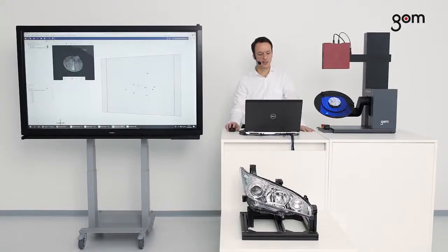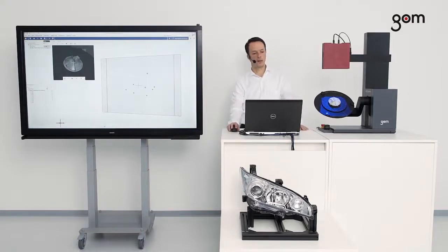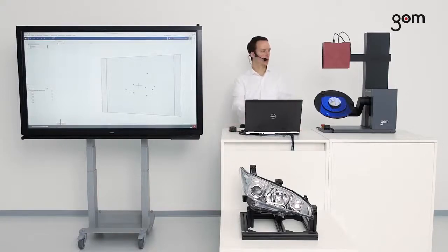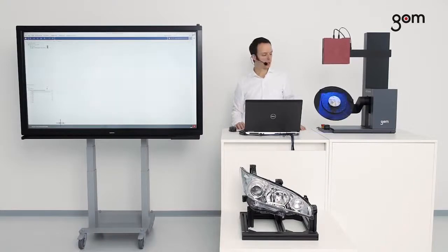First of all, I need a mesh of the cover. So, in a parallel project, I will run a measurement series. Right here, I am using an ATAS ScanBox port. I already prepared the bottom of the cover and will now measure the top of the cover. The transformation into top and bottom is performed by joint reference points, which are visualized in both measurement series.